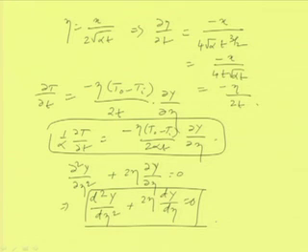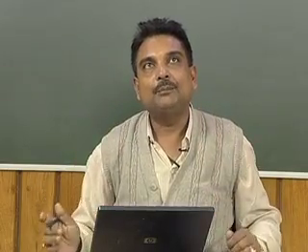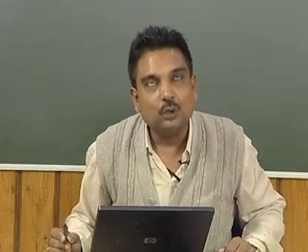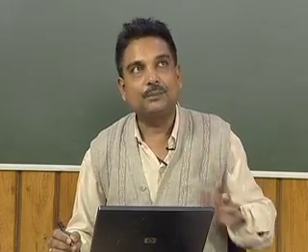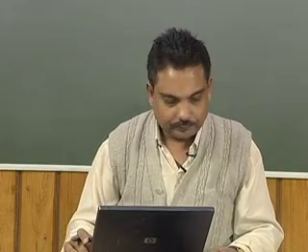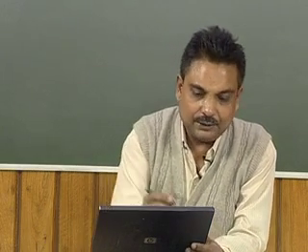And in this reduced governing equation, we have got the boundary conditions already decided for this case. These boundary conditions we got when we assumed that the left face of the body is suddenly placed to a temperature T naught, which is lower than the initial temperature of the body. Now, if we solve this equation, then we will get the solution of this equation.